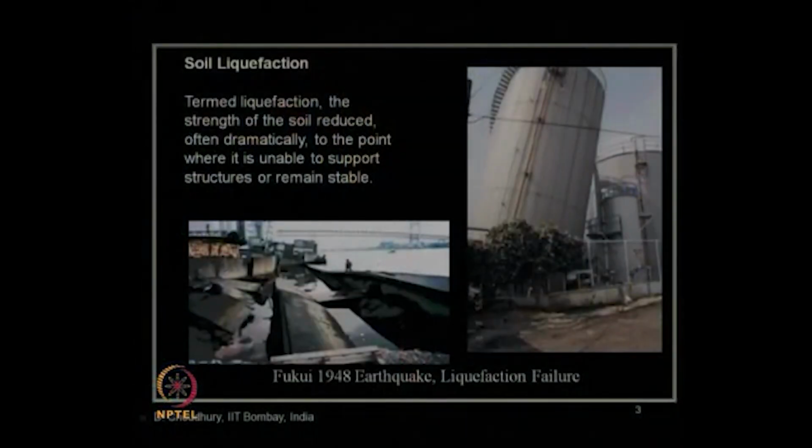During the liquefaction process, if some soil on which a foundation has been constructed for a superstructure gets liquefied, or flows like a fluid or behaves like a watery material, obviously one can easily understand that the total structure constructed on that soil cannot remain stable, but it has to collapse or tilt or could penetrate inside the soil strata.